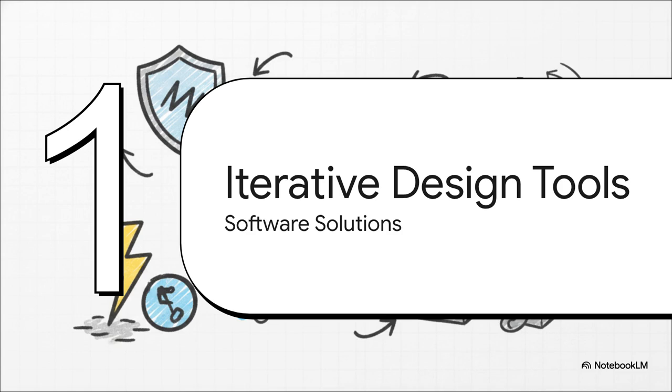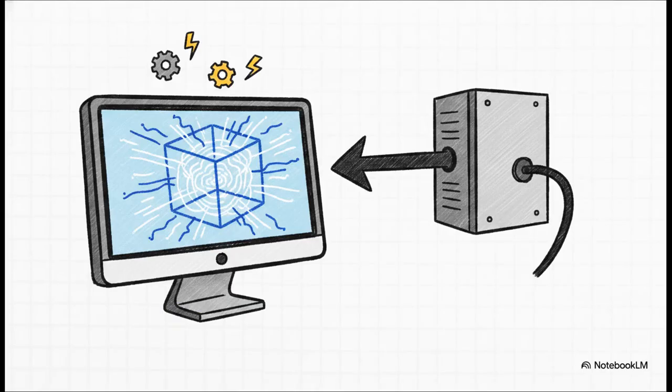Finally, Section 5, Tools for Iterative Design. Modern electronic routing is basically a maze of complex branching networks and totally unpredictable stray capacitance. Trying to figure out your shielding strategies, coax choices, and physical routing? You really need specialized system-level solvers to accurately predict how the EMI will behave. Software tools like Zuken E3, Siemens Capital, or ePlan are great for handling the heavy lifting of harness architecture. And then you have hardcore electromagnetic solvers like ANSYS, FEKO, and CST to simulate the 3D field interactions. They predict exactly how your physical layout will actually perform before a single piece of copper is ever cut.